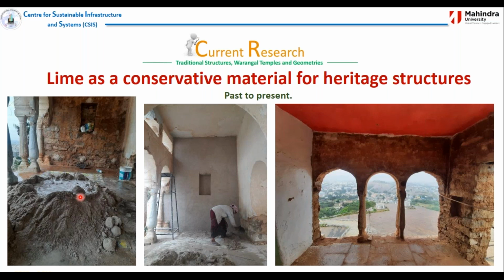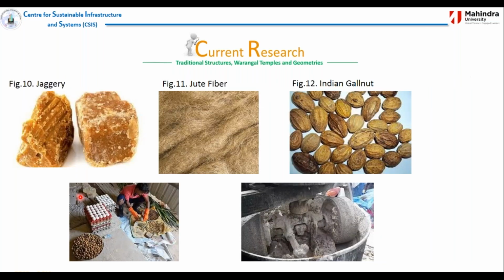Now those cubes we will be testing over a 5-year period, because lime is one such kind of material. I'm sure if anybody is from the Archaeological Survey of India or has been in the conservation of heritage structures, they would know lime is a material which, with the right proportion, can gain strength over a period of time. Calcium carbonate forms over time, and the strength will increase, but it depends on the composition of lime. So the composition which we were using is this.